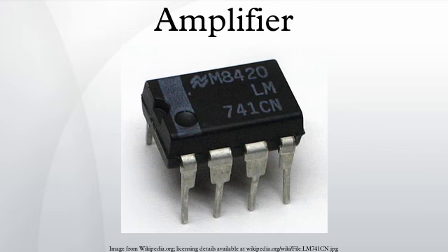A single Class B element is rarely found in practice, though it has been used for driving the loudspeaker in the early IBM personal computers with beeps, and it can be used in an RF power amplifier where the distortion levels are less important. However, Class C is more commonly used for this.